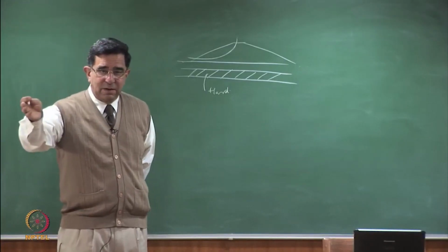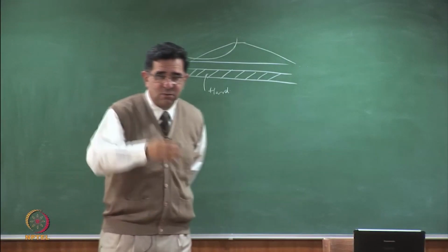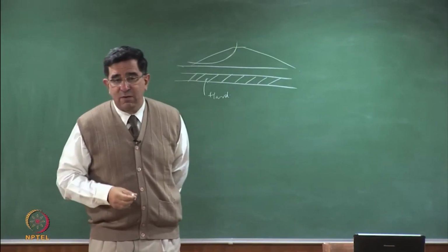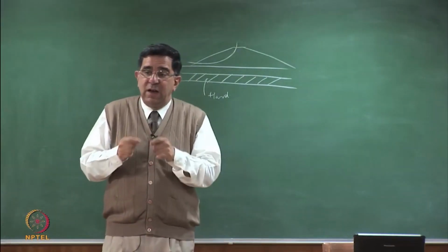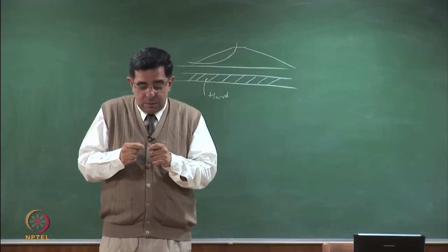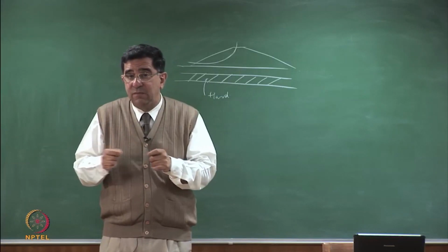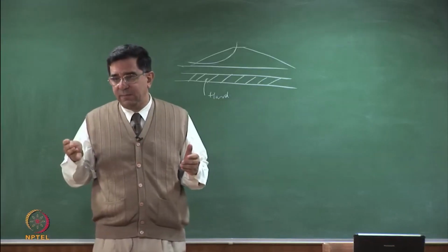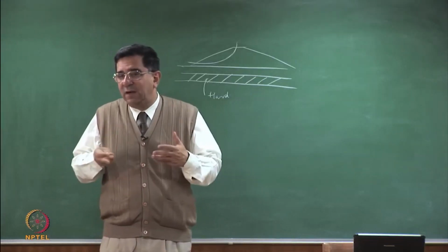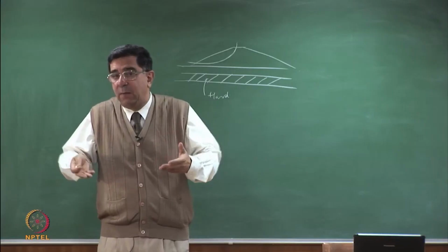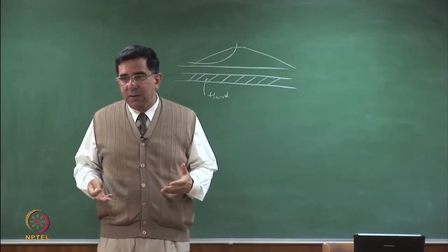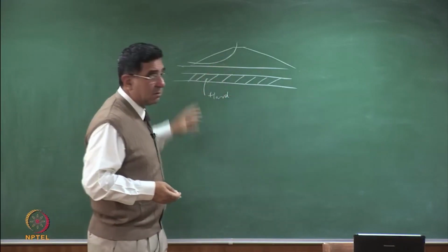So somebody said hard surface, now somebody said weak surface. What kind of weak surface do you have? So a failure surface will have to go through a straight line if there is a weak surface along a straight line. If there is a hard surface, the failure surface will tend to remain above it. Like if you have rock, then the failure surface will remain above it.